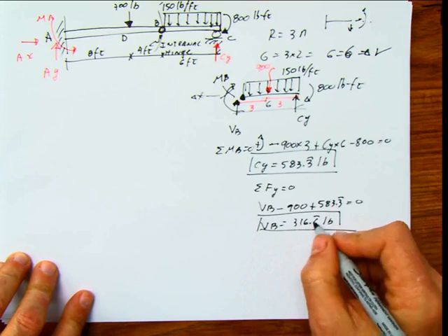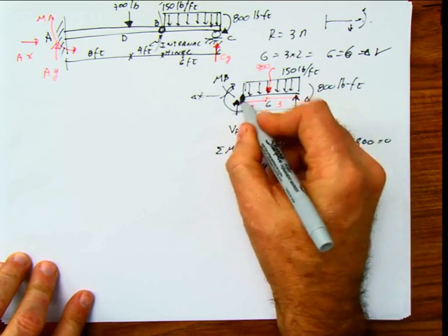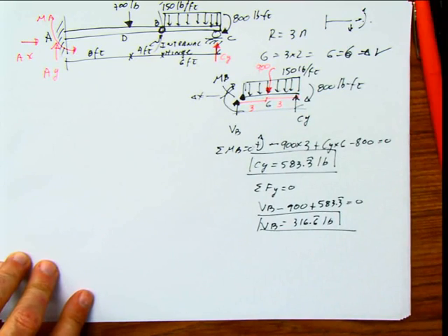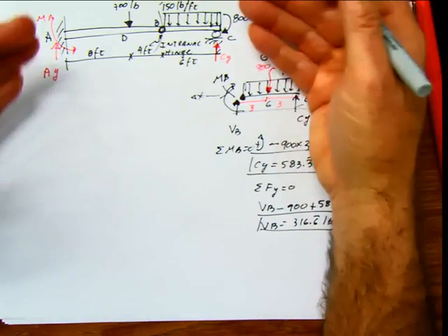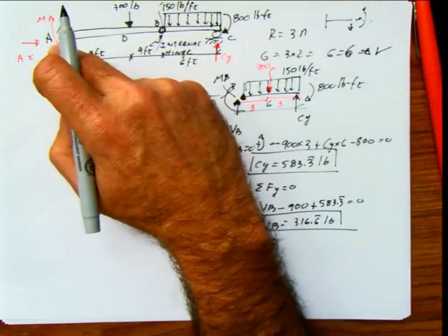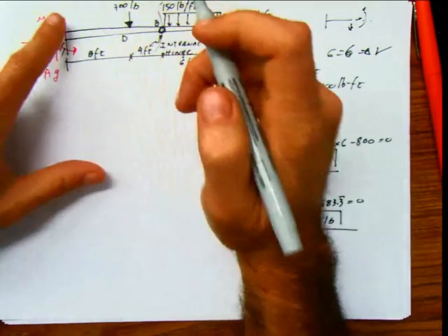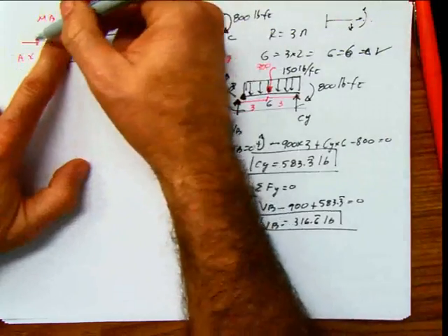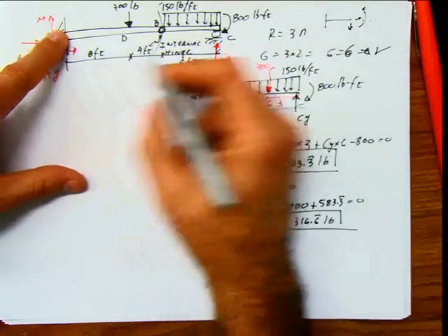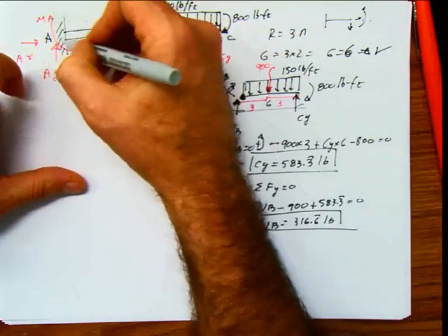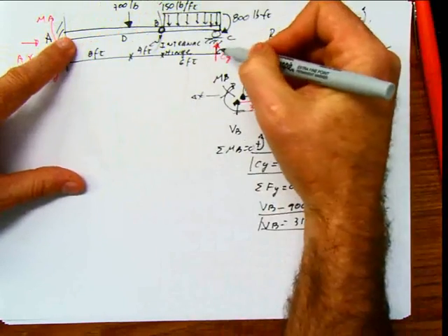That's going to be the value of the shear at the hinge, which I don't need for my external reactions anyway. Okay, now once I have that, I put everything back together, and then I can do summation of moments in my whole beam here. I have 2 unknowns, because this AX is also 0. The only unknowns that I have are the moment here and Cy.